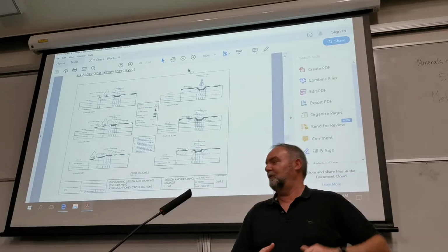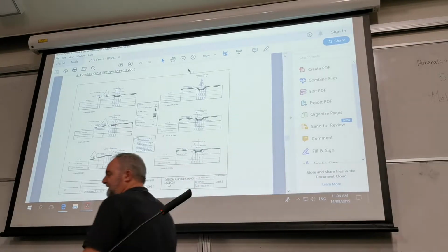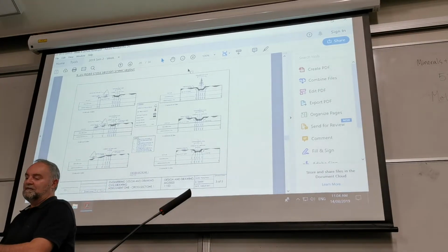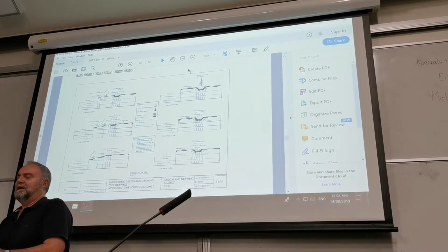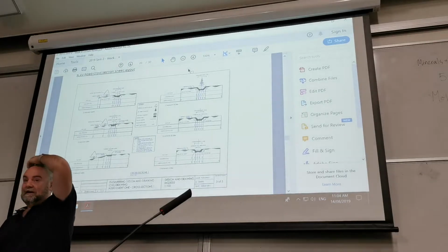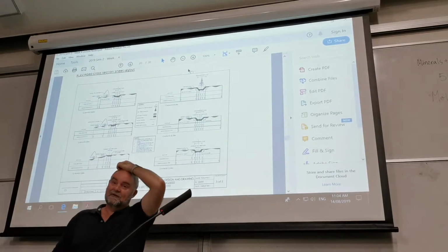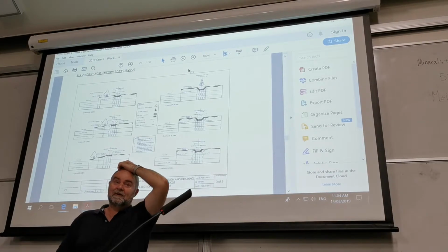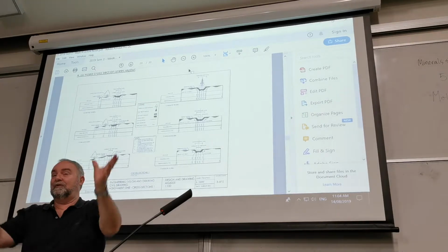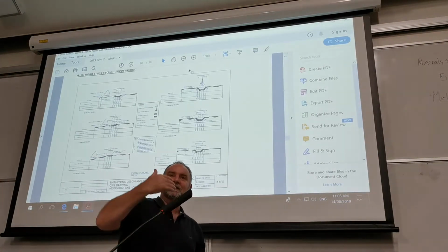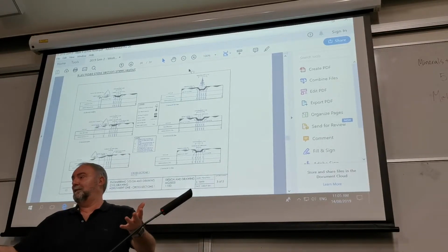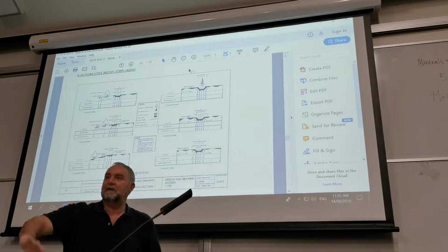It gets more critical when a surveyor does not pick up something. So he might be asked to do a road every 5, 10, the norm is 20 metres, and he completely ignores a great big rock outcrop. Now, if you do that in central Otago, that's dynamite territory. You need dynamite to get rid of the schist rock. And if you ignore that as a surveyor and just move on to the next cross section, you've ignored quite a few $100,000 worth of work, right? Just like if you ignore a great big hole in the ground.